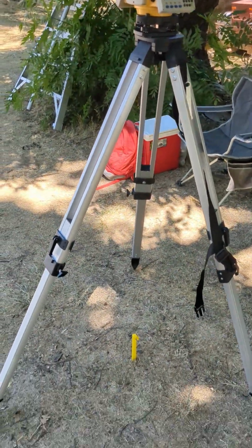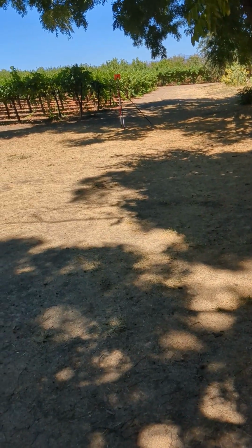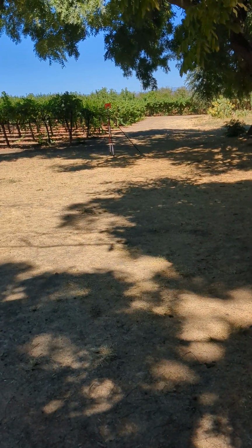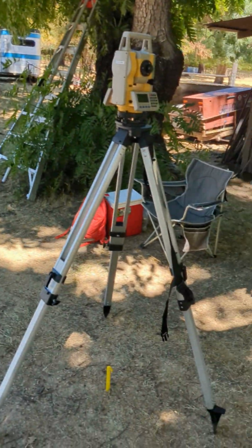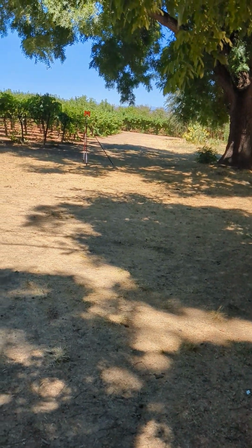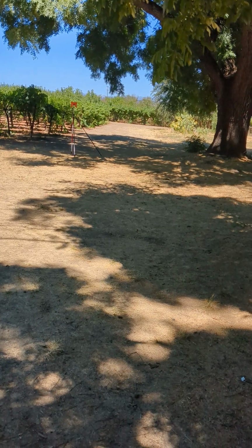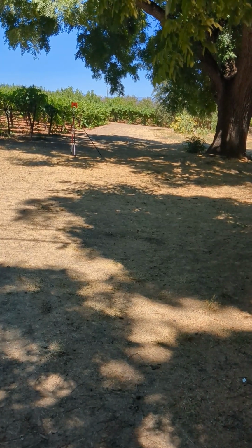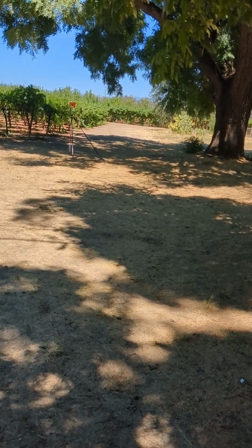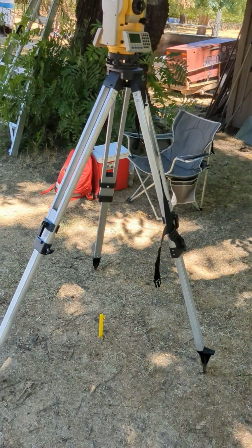So right now I'm positioned here, and there's my target, and I know now what the UTM is for that target. So I'm going to move my total station over to my target and actually put the target back over here, and I'm going to try to reverse what they call backsite to find the reference of where that location is, and to calibrate the total station back to this point.